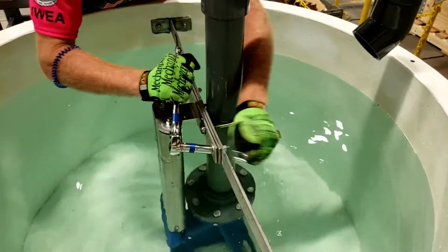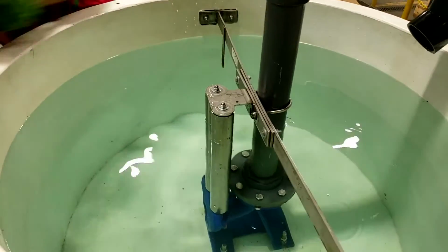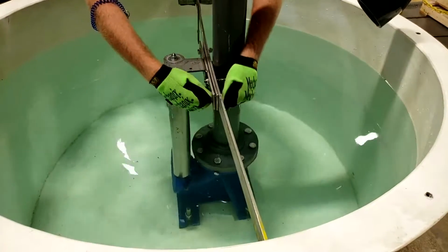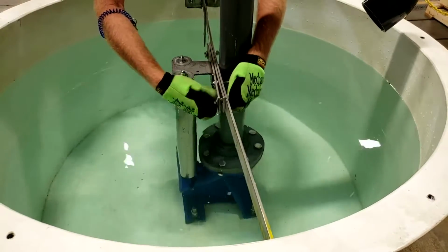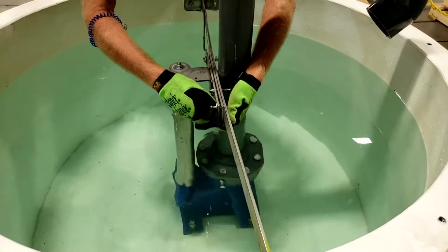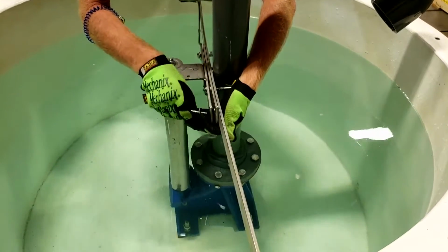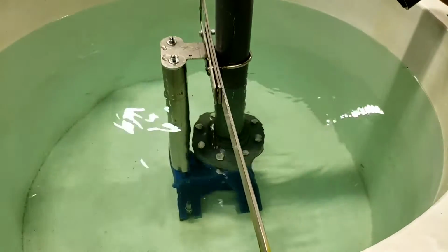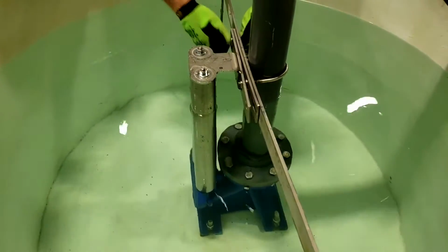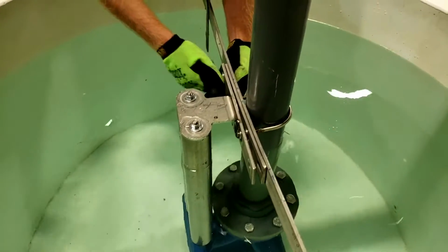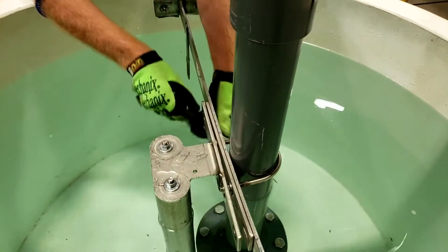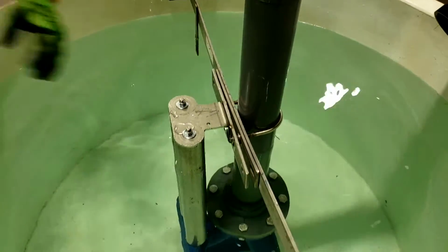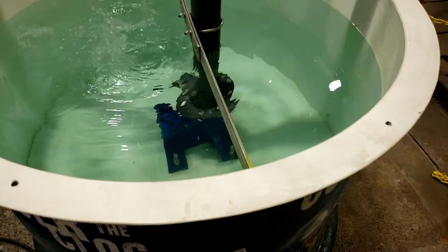Remove the 2 9/16 inch bolts with washer, lock washer, and nuts from the guide rail flange. Be careful to not drop any tools, bolts, washers, or nuts in the wet well. Once the bolts in this step have been removed, you can remove the flange and both of the 2-inch stainless steel guide rails from the wet well.